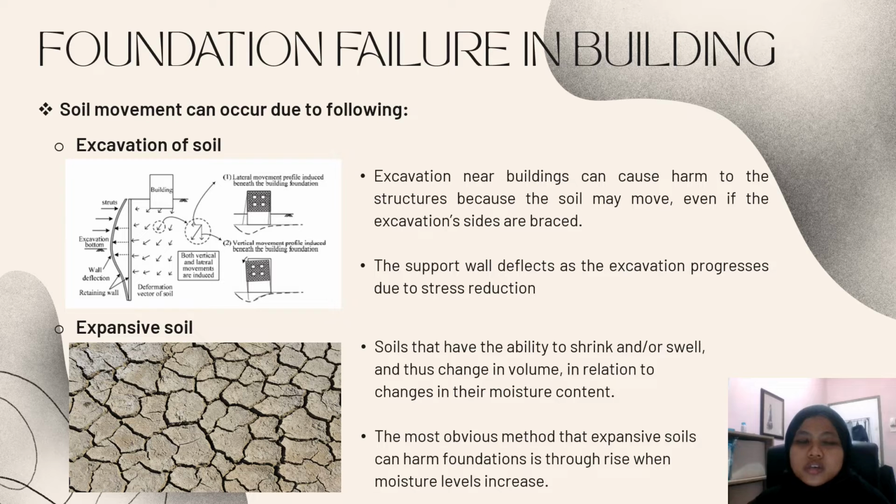Okay, so what are the causes of the soil movement? Soil movement can occur due to excavation of soil. Excavation near buildings can cause harm to the structures because the soil may move, even if the excavation sites are braced. The support wall deflects as the excavation progresses due to stress reduction.